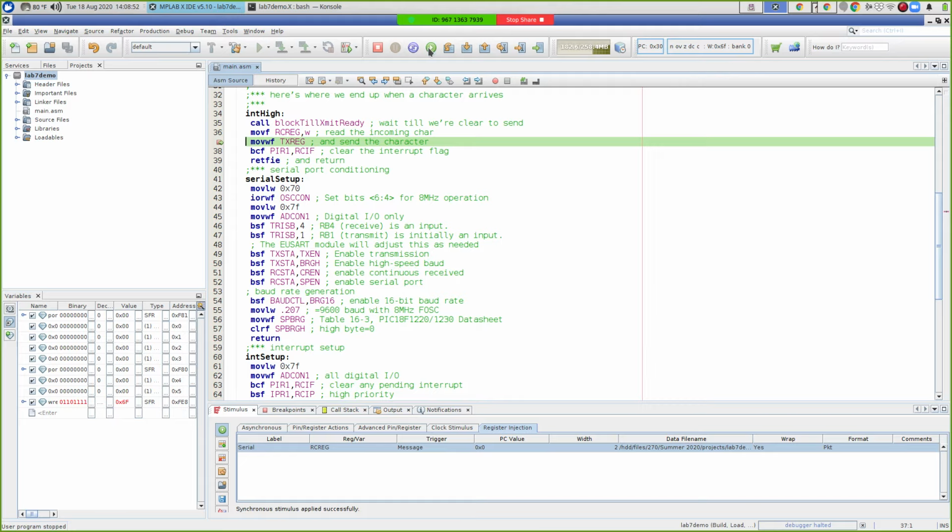There's W-O-R-L-D. There's an exclamation mark, hex 21. And if I run again, it will repeat the process. It'll go back to the beginning of the file and read the next character, which is back to our uppercase H. So we're actually reading the contents of this file inside our PIC code. And the file is being used to supply the input.